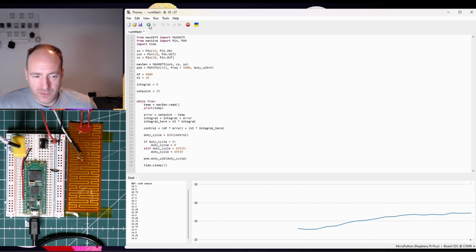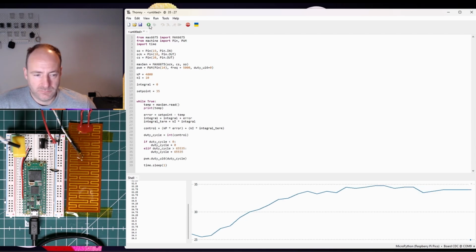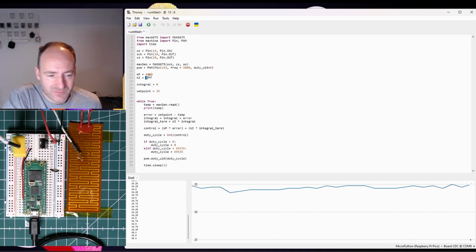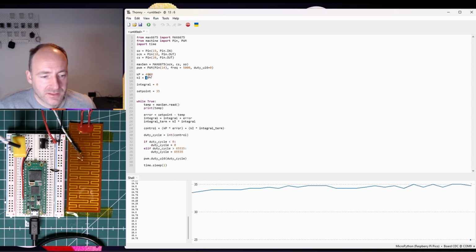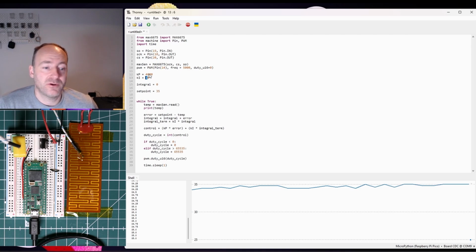And there we are, we've not overshot now, but also we should actually creep towards 35, we're quite close. See, we're actually on 35 now, that's not bad at all. There's no offset, the integral removes the offset, and that's the important point.